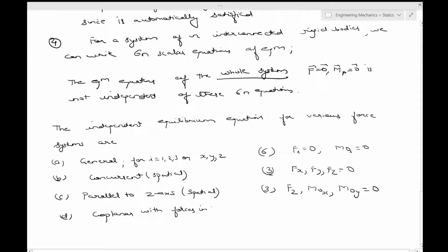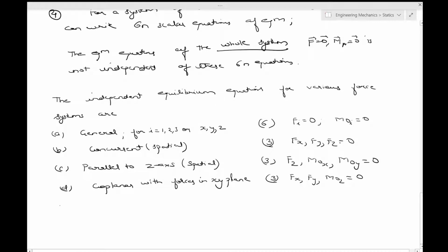Now if you look at coplanar with forces in the xy plane, this would be Fx, Fy, Moz equal to 0. Similarly, coplanar with forces parallel to the x-axis in the xy plane, you have only two equations, Fx and Moz equal to 0.